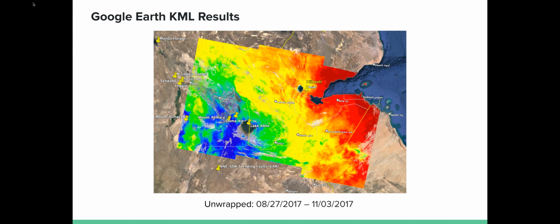So I was able to use the Google Earth Images layer and found that someone's uploaded images actually show that there are isolated springs that would otherwise be mostly unexpected for this area, and that there is vegetation in these regions where there's low coherence. One last thing that I noticed from looking at this image in this way is that there's some wavy artifacts that are preserved in the interferogram, and they appear to somewhat be aligned with topography. So from the lectures this week, I think that this is evidence that I'm not removing the atmospheric noise sufficiently. So this is another source of noise that I will have to work on further.